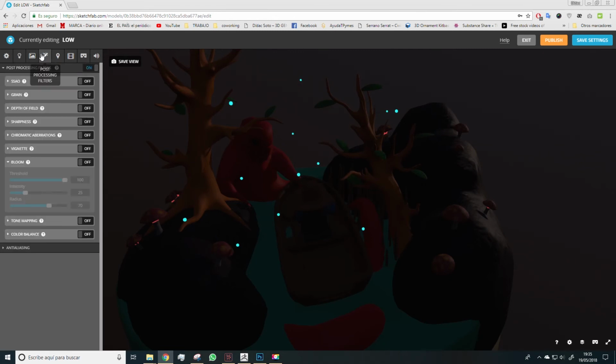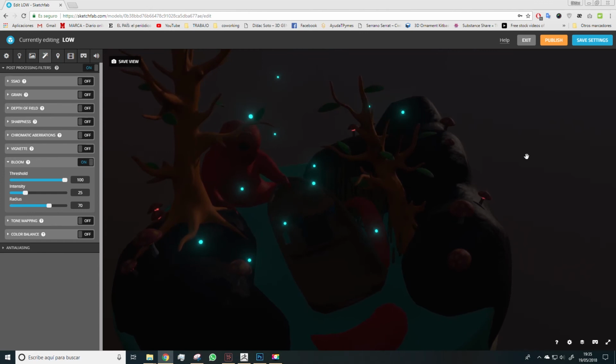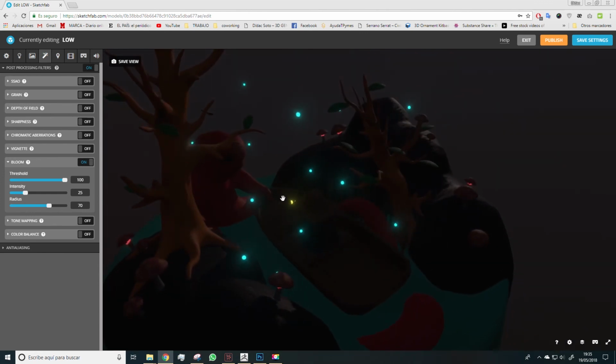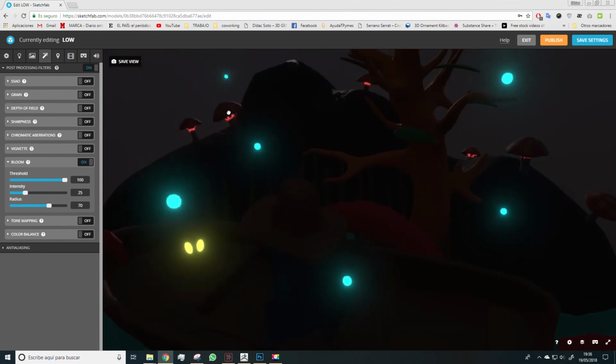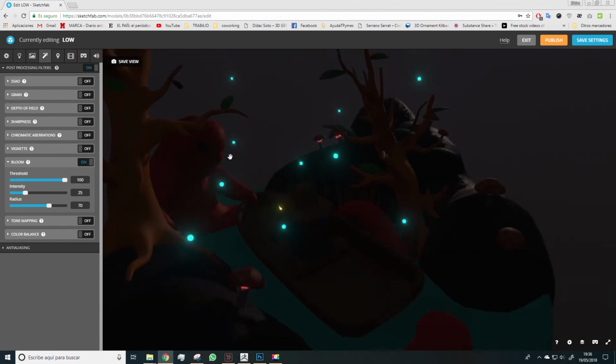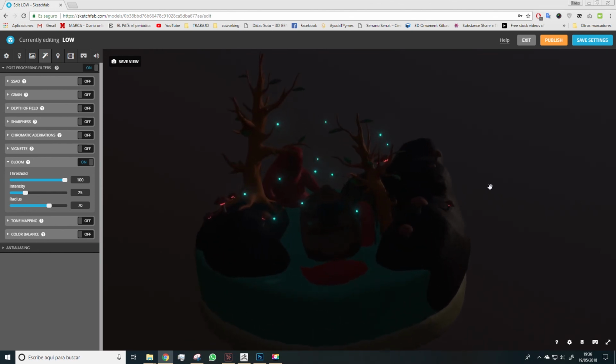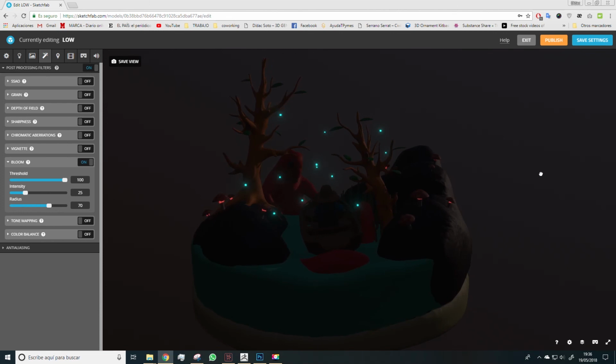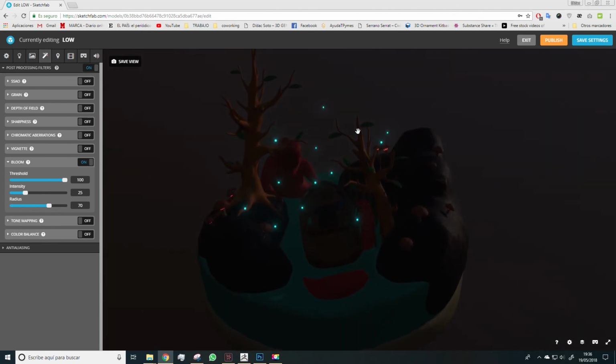Click Open and we'll illuminate those parts in the illumination map. Now for it to look better, we navigate to the Post-Processing Filters tab and we enable Bloom, and by doing this, we can already see those parts in the emission map start glowing. The gills in the mushrooms, the lantern and the spheres. All right, so we'll end this part of the course here. And in the last one, we'll see how to get the image using Sketchfab and get a nice model. So we'll leave it here and see you in a bit.